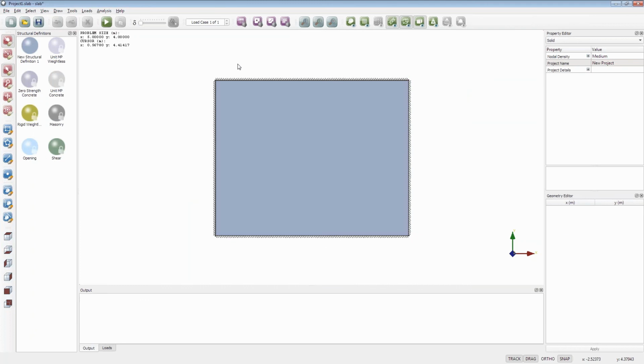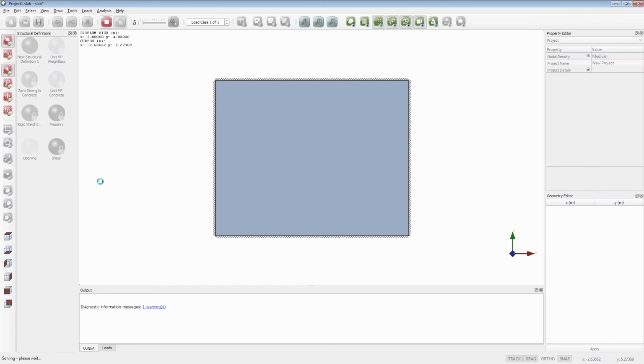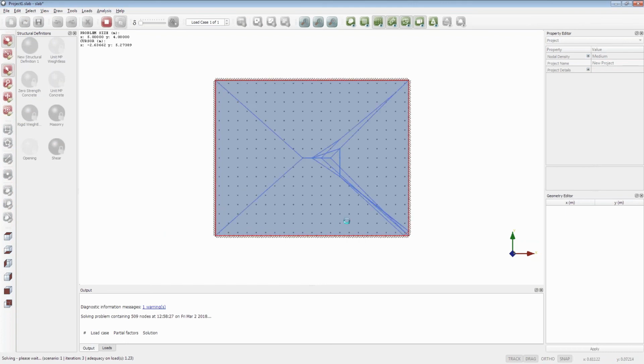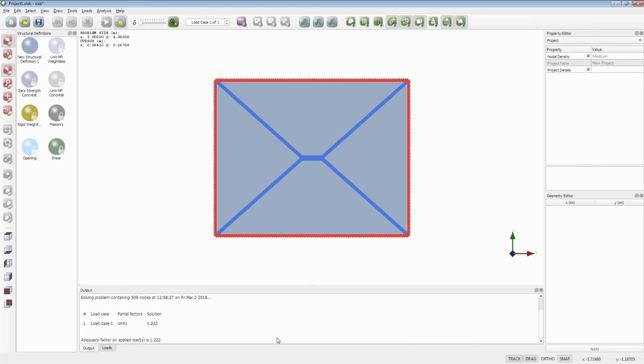And I click finish. We can see here we have our problem set up. We have the simple supports around the outside, and if I click on here you can see that the loading is applied to the entire slab, and then I can just click solve, and the software goes through a number of different possibilities until it finally finishes on this envelope type mechanism, which is obviously something that should be quite familiar from textbooks and things like that.